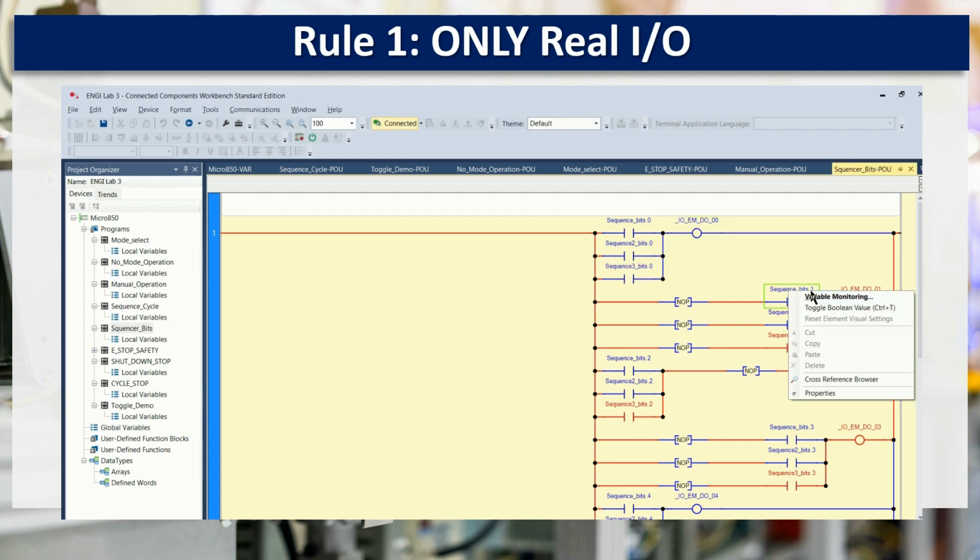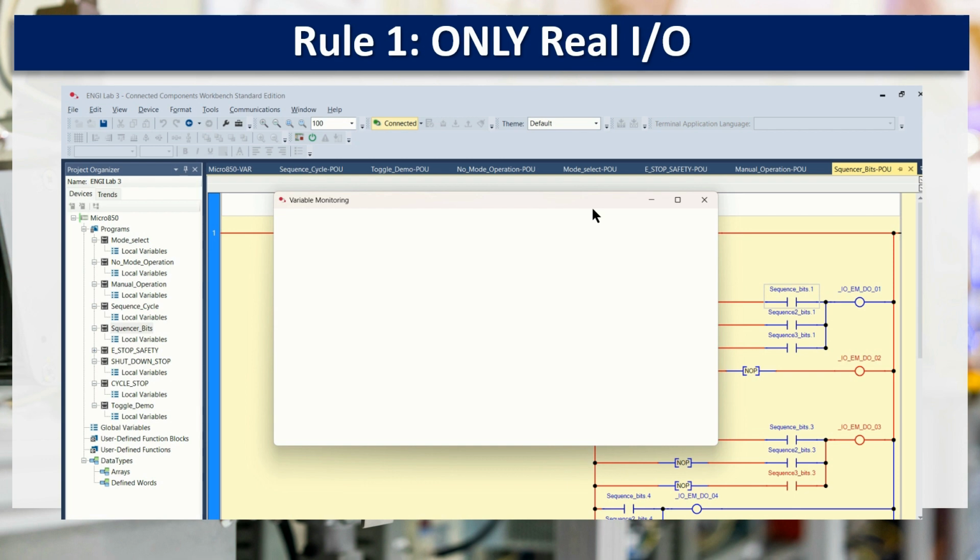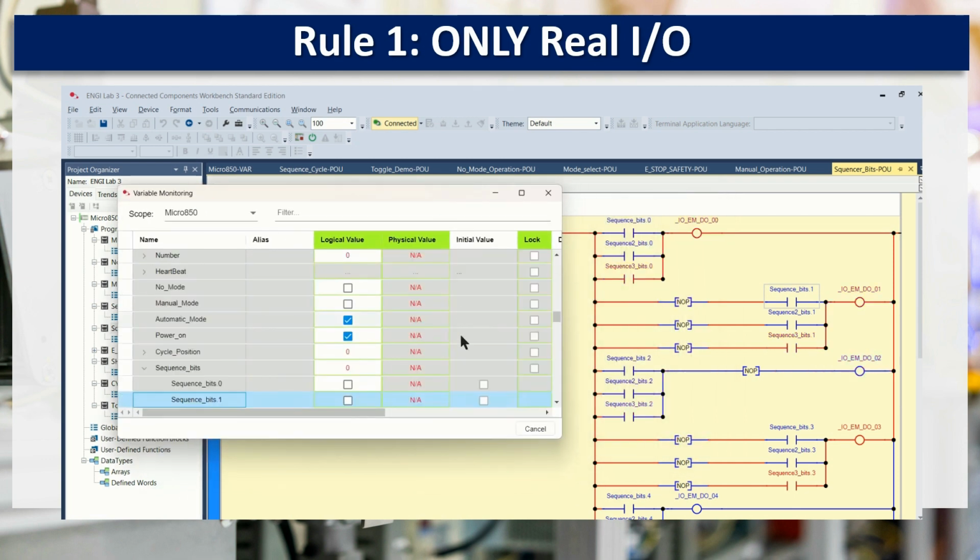Now, when we talk about manipulating bits, we also tend to think of DINTs and INTs and SINTs, etc., as being homogeneous and a single data type. As in, if I have a value of 32,768 positive, it's got to be in a DINT, and that's just a decimal number represented by a stream of bits. We can also use the bits individually, and that means we're allowed to manipulate them.